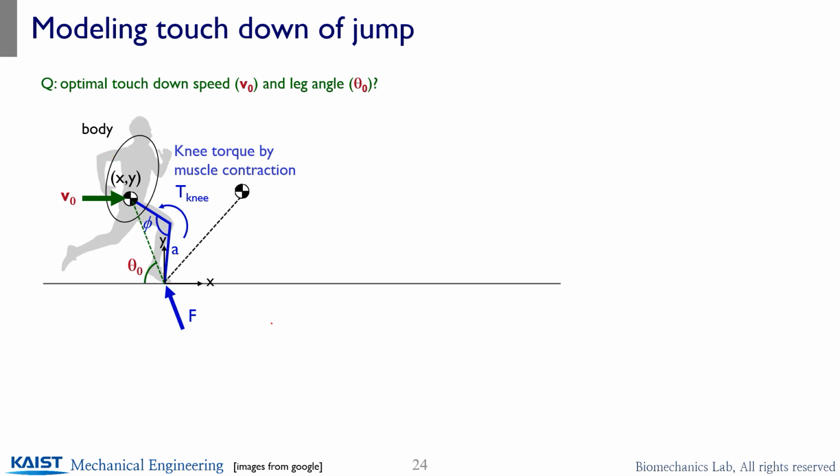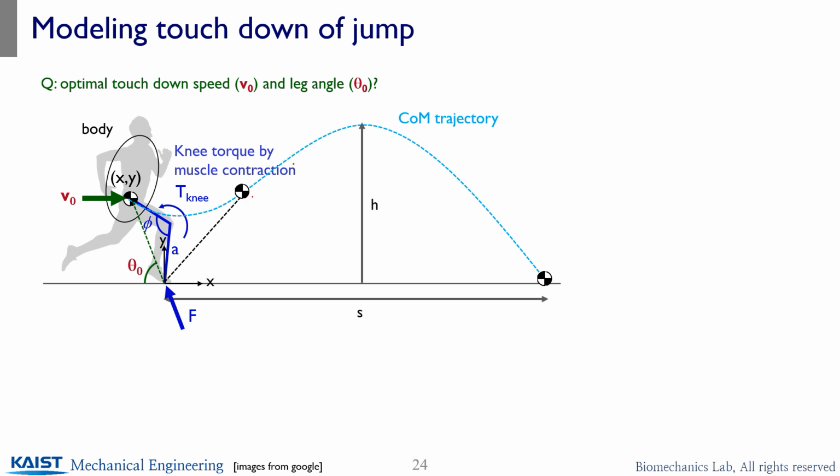So what's going to be next? Since we set up the point mass model for the stance phase, the next step is what happens after that. During the stance phase, we just apply the equations of motion. But when the takeoff occurs, there is ballistic falling, with only gravity downward.